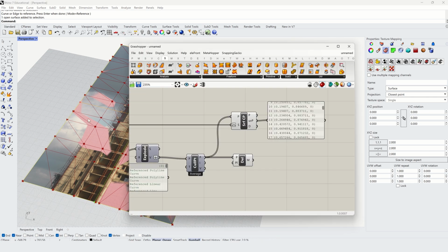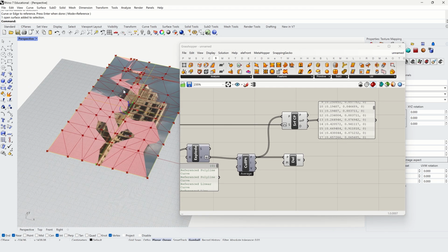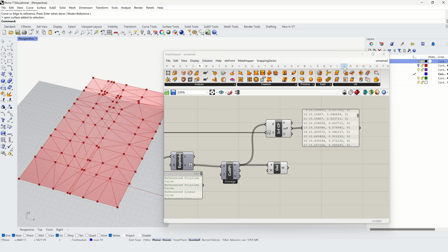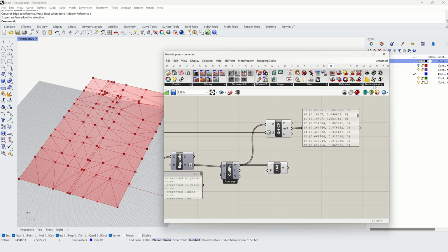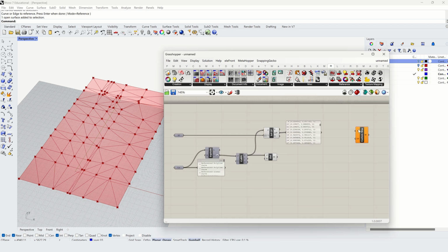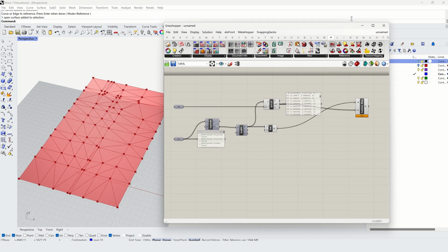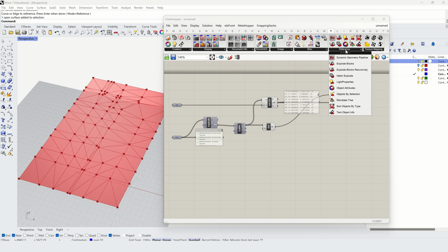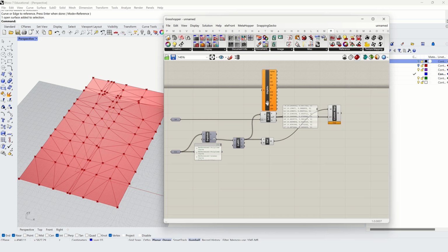For the next steps, the mesh should not have an even surface mapping, but be mapped such that every point holds a consistent UV coordinate reference, no matter where it is moved to. Returning to Grasshopper, select the Human tab and find the Texture Mapping tab. Select the rubber ducky, Custom Mapping, and place it on the canvas. The M mesh input will come from the Delaunay mesh, and the UV coordinates input will be the UVP output of surface closest point. This doesn't change anything visible, but the output mesh is different from the input mesh because it now has the texture mapping information saved in it. Using another component from Human, Object Attributes from the Reference tab, you can extract the material from the surface.